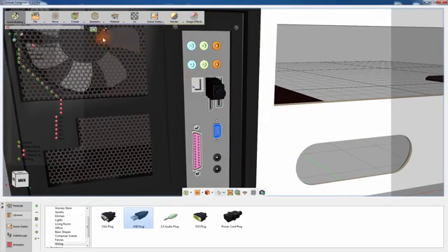From the Create menu, select Paths, then Composite Paths, since creating a wire requires a path to serve as a guide. Set the Creation option to be in 3D space and click OK. There are several types of composite paths, but we will be using the B-spline path since the flow of its curvature mimics the appearance of wires.